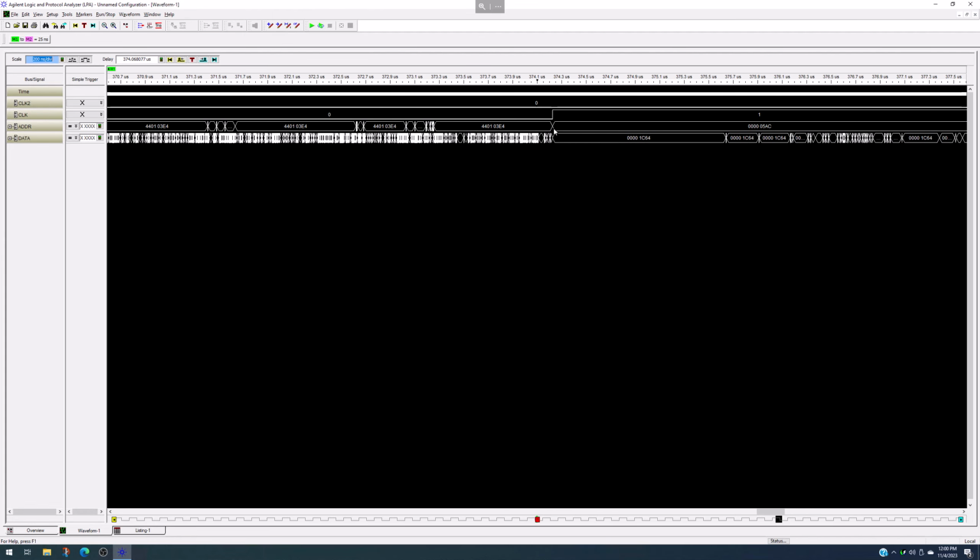Okay, so here's a spot where CLK went high. And so this would be valid according to the processor at this stage, most likely. There are other signals we have to look at, but I'm at address 5AC, and I can see that the data value was 1C64 when that rise happened. So that starts to help me understand what's going on.